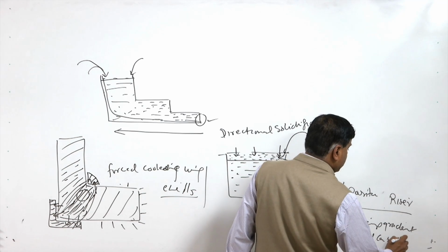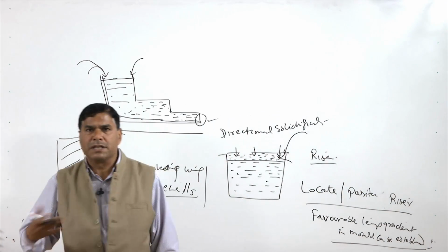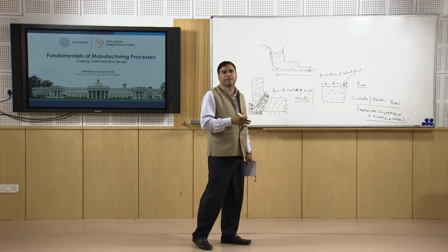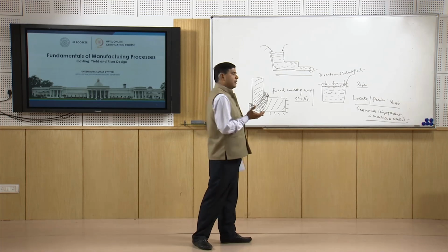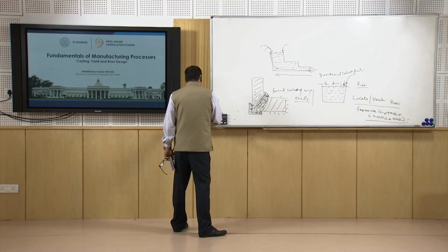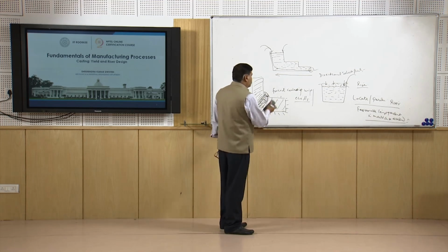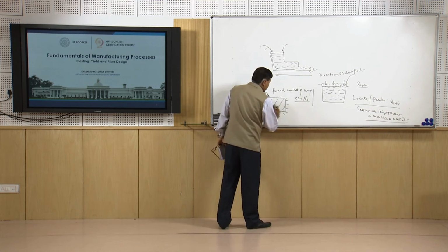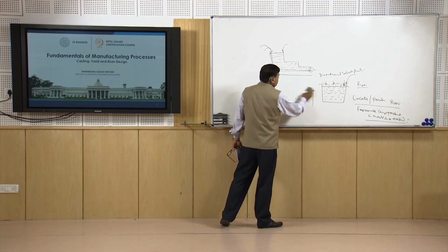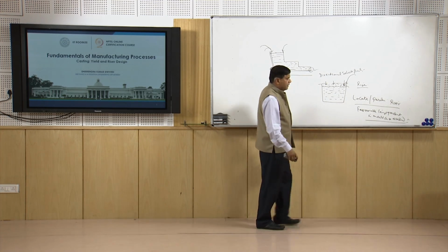can be established. So, basically chills are providing localized cooling in the areas of the hot spots, so that those zones can be solidified at a much faster rate, and the hot spots from those areas can be avoided, or those hot spots can be eliminated through the use of chills by applying an increased cooling rate, so that the shrinkage cavities can be avoided.